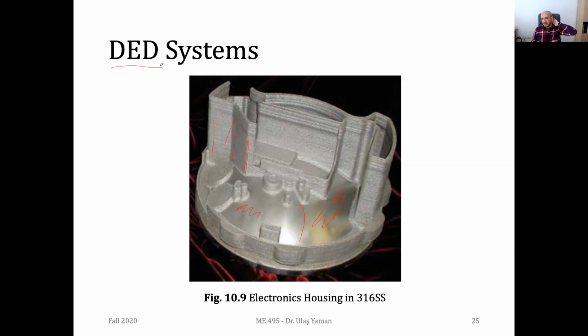There's a question on the chat. Hussein is asking whether the shielding gas can decrease the size of the heat affected zone. No, it's not related, as the heat affected zone is just related to the amount of energy you're applying into that region. So it depends on the power of the laser, the type of the laser, and the material itself. The shielding gas is just providing an atmosphere to avoid any oxidation inside your parts.